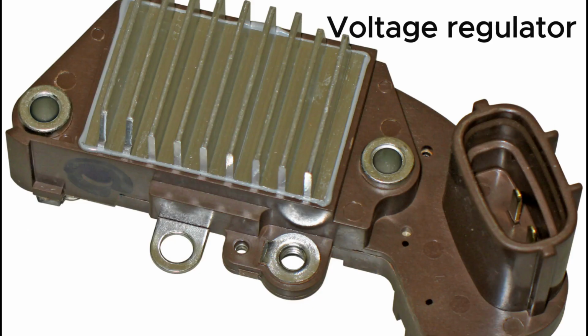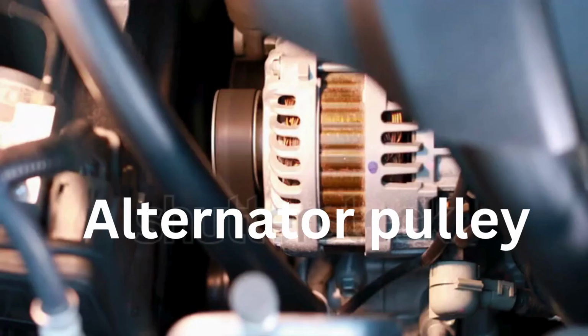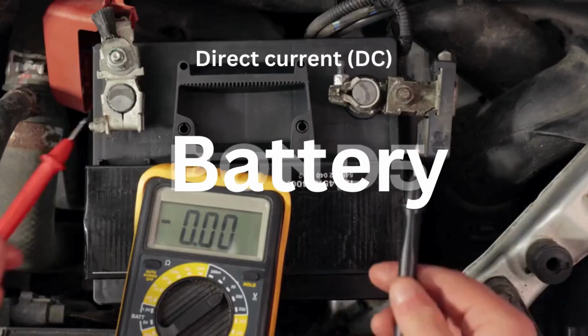Voltage regulation. The voltage produced by the alternator can vary depending on the speed of the engine and the electrical load. To ensure a consistent voltage output, alternators are equipped with voltage regulators. The voltage regulator monitors the electrical system voltage and adjusts the field current supplied to the rotor to maintain a stable output voltage.